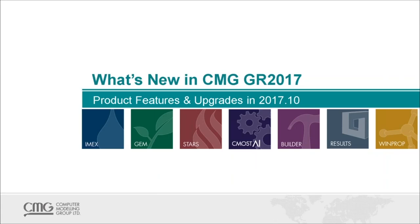The next question is, what is the difference between modeling of polymer in IMEX, STARS, and GEM? So IMEX, as we talked about, had a couple of big new improvements for more accurate modeling. However, I guess STARS and GEM would still be our most complete modeling packages for modeling polymer injection. Some of the features that would be included in STARS and GEM compared to IMEX is that STARS and GEM can model polymer viscosity versus salinity, and another area is polymer adsorption versus salinity. So basically, we have more salinity effects in STARS and GEM compared to IMEX.